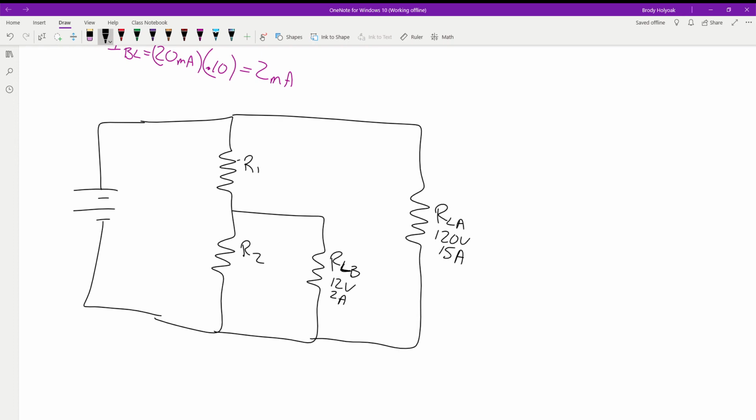This is what we're doing: we're getting this so we fill it up faster and we drain it faster, so it doesn't take as much time in between loads. In this case, yes. So that's what we have to determine. Where is our bleeder current going to go? What's the definition of the bleeder current? Current that's not being used by the load. So we have two options to put our bleeder current. It's still going to be 10%. So our bleeder current, where is the current going to be that's not going to be used by the load at all? It's going to be R2.